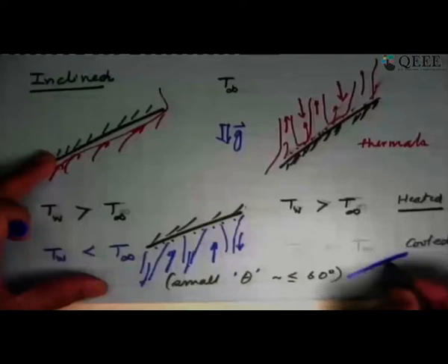So you have this plate over there. This is colder than the air. So all of this will come down, will form a nice boundary layer, and will start going down. So at least these two cases, we can approximate that it's a slight deviation from the vertical plate. And the deviation is taken care of by the fact that the force that is going along the plate, if this is theta, this is g cos theta. So as a first approximation, we can use the vertical plate correlation, replace g by g cos theta, and get the same solution.